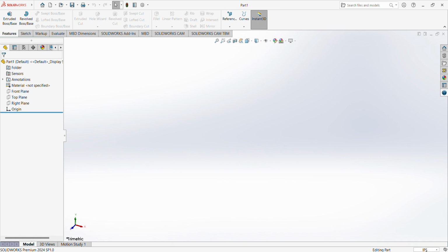So at the bottom part of your window for your SolidWorks, you have this page that usually starts with IPS. So basically it shows you the different units you can work with. So depending on the dimension of what you're working with, you pick it. Me, I normally work with MMGS. Okay, so apart from that, that's basically the only thing you need to worry about at the bottom part for a beginner.